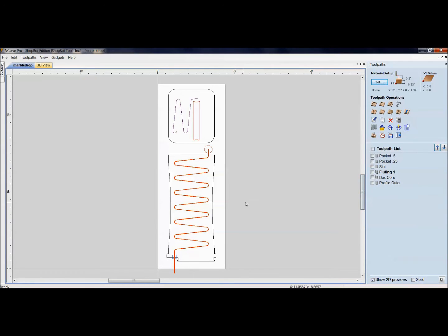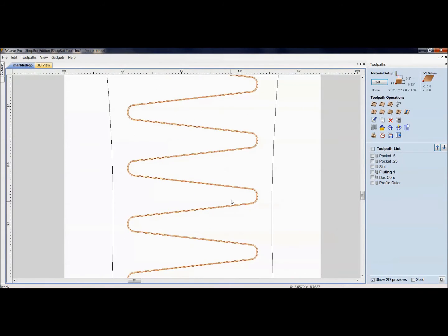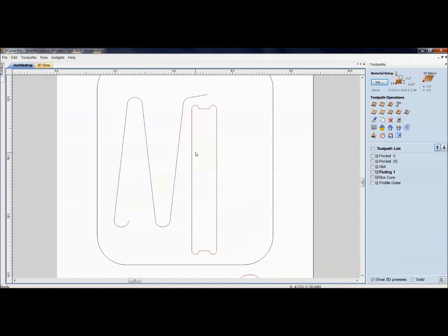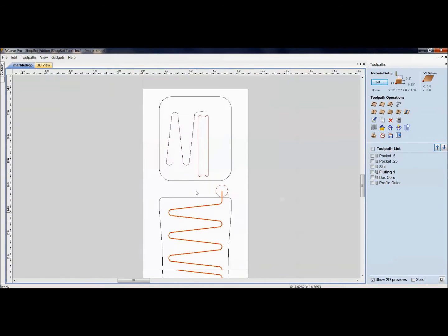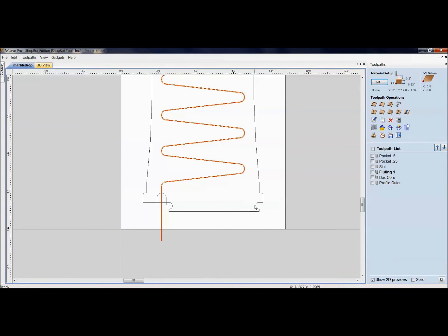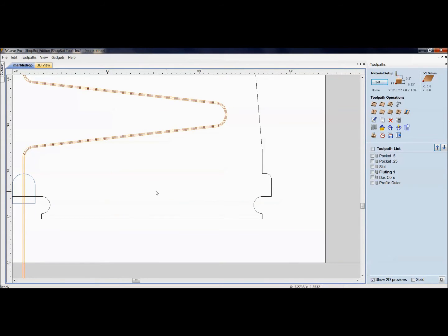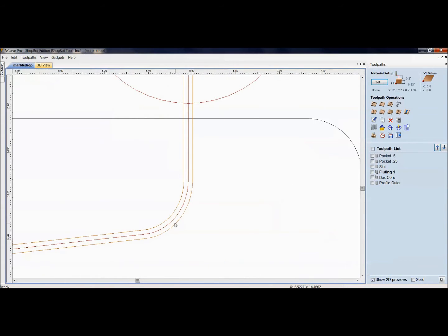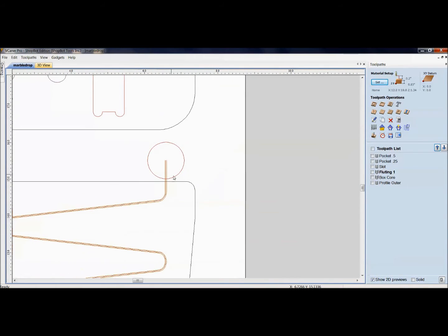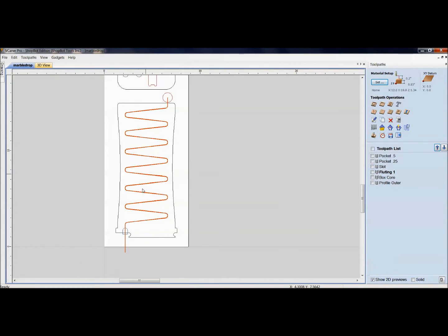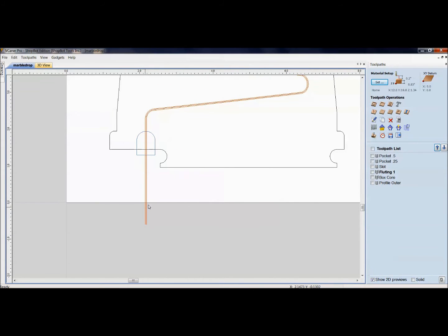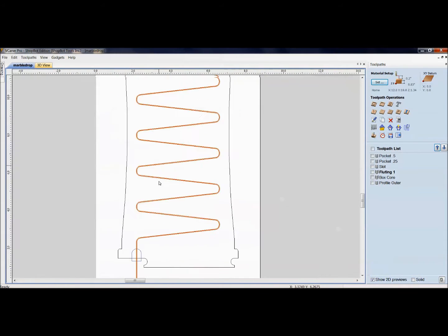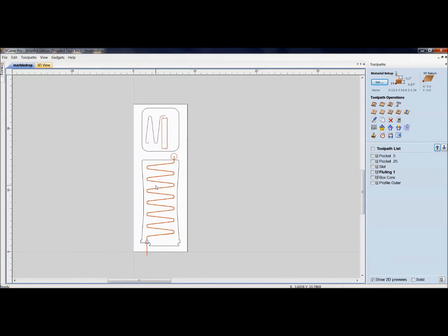So this guy here is our 2D view, and we've got just the different areas. Here's our base with a pocketed out slot. Here would be our slot that's going to go down in there. There's a big dog bone because it's cut with a 3/8 bit. We can see where our marble track is. We have multiple lines on here, and you'll see why here in the video. You have a circle here where this is going to be pocketed down for a lead in, and we also have down here where the lead in or lead out starts off the material. So with that said, let's look at the video and see if we can see more about why this file is set up the way it is.